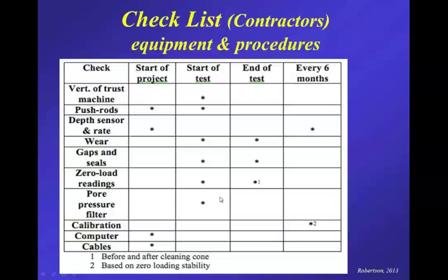Saturate and change the porous filter at the start of every sounding. That's the preferred way. Certainly saturate it at the beginning of every sounding, and ideally if you're using relatively inexpensive porous plastic filters, replace the filter for every sounding.